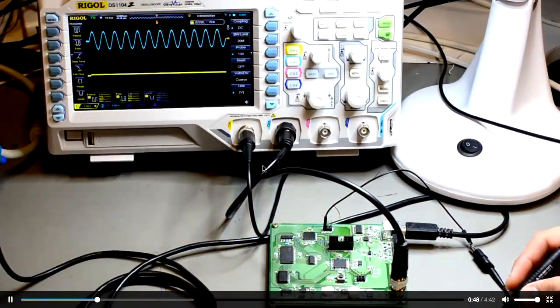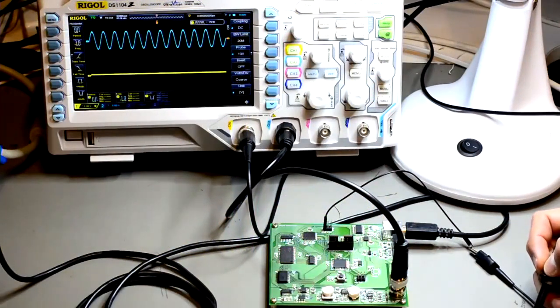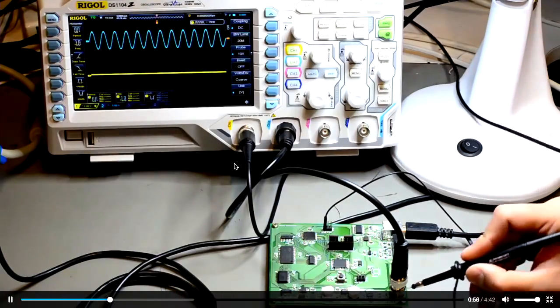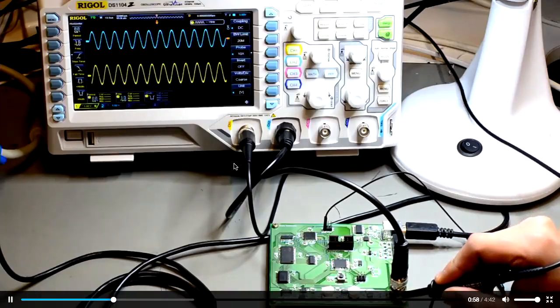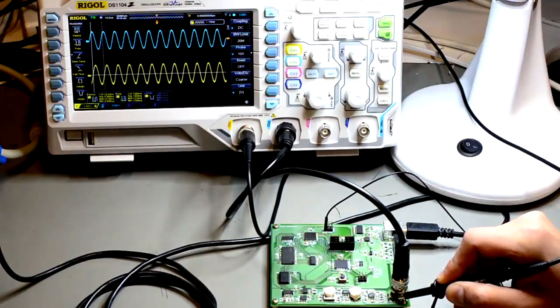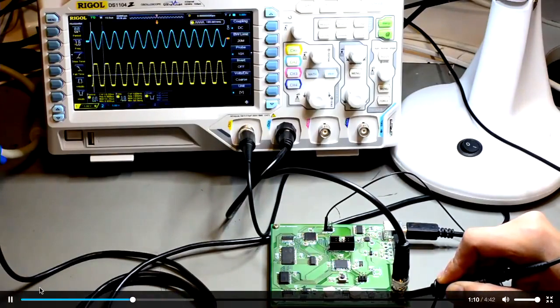Okay, so now we're going to go through the front end of the DSO. This is the signal path from the input all the way up to the ADC. The first thing I'm going to show you is the input protection circuit. You can see that we're giving it a 5 volt amplitude signal and we're getting a 5 volt amplitude output. And if we were to increase the amplitude of the input signal, it clamps at 5.6 volts as expected.